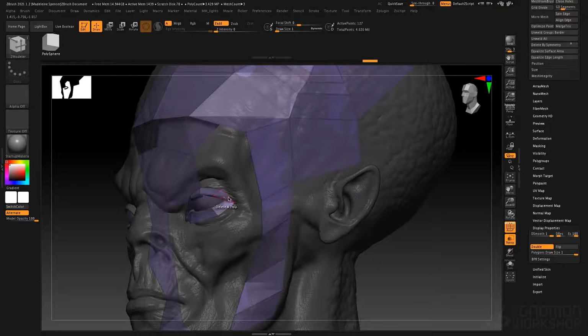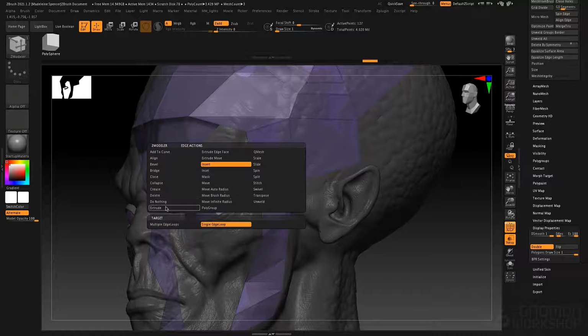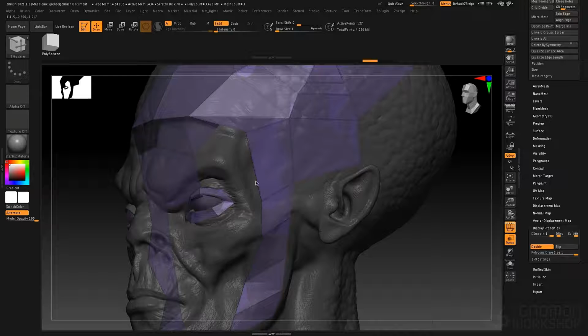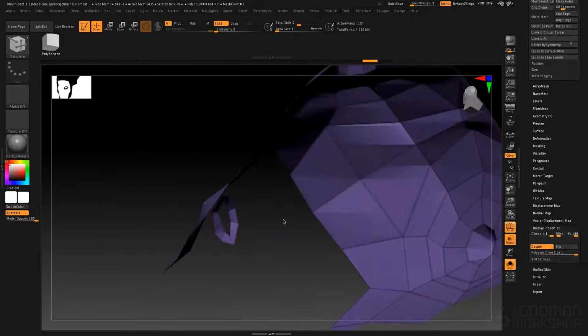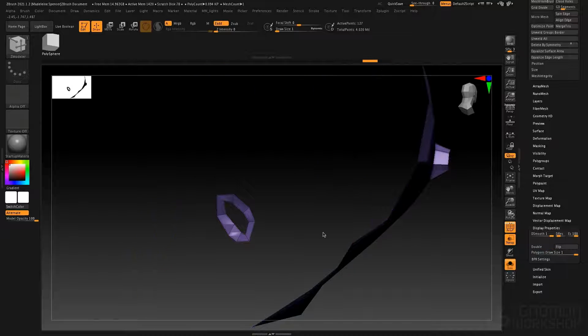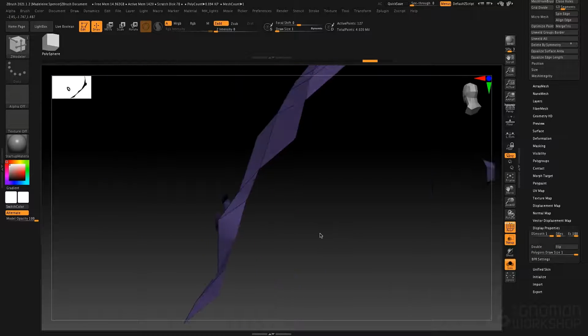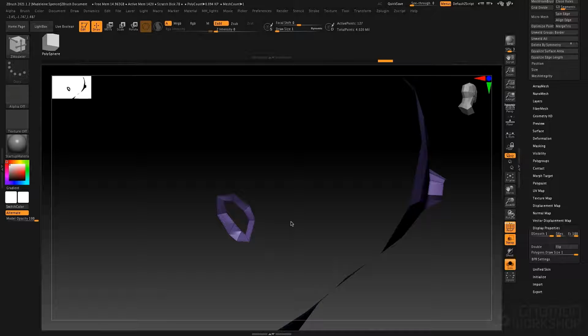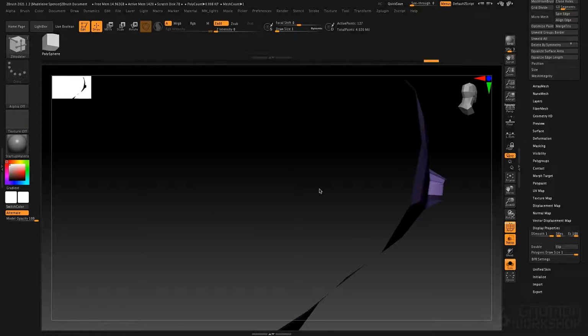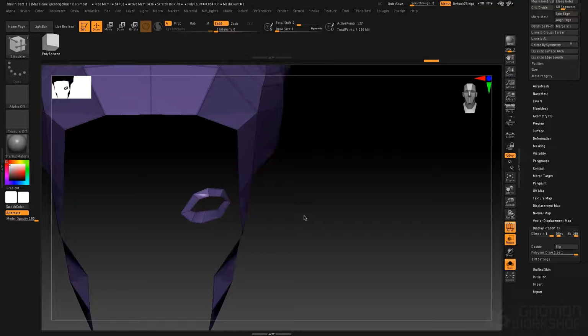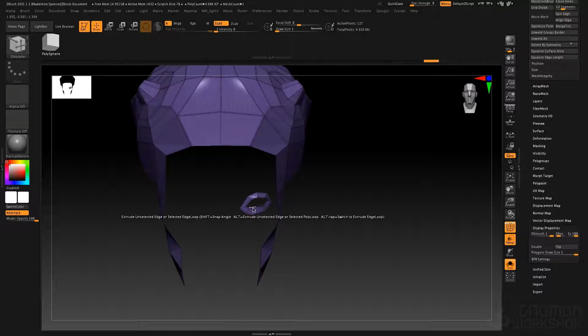And now I will just grab this edge and make sure that I'm on that edge, and I am on Extrude, and then click Drag. Now again, you see what's happening is, if I click that, I'm not actually getting anything. So why would that be? Well, let's rotate around to the back, and let's turn off double-sided, and you see our normals are not consistent. It's easy enough to fix. I will just isolate this and flip that, make everything visible again,